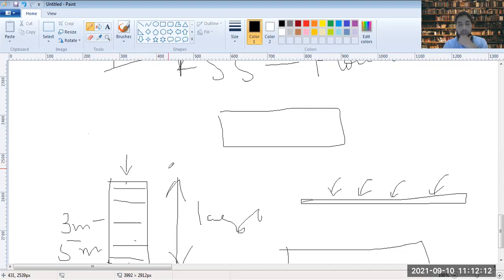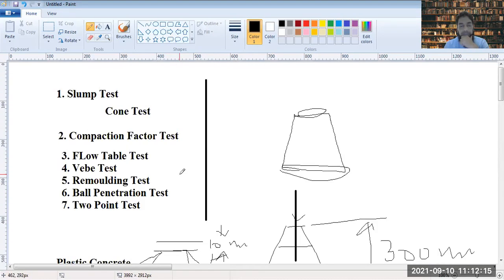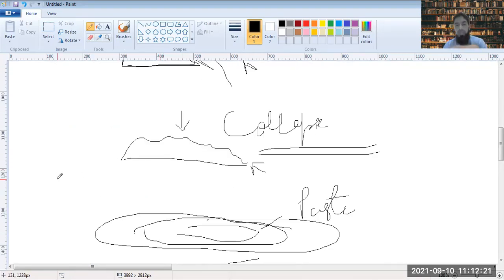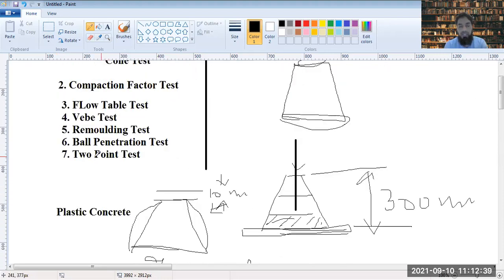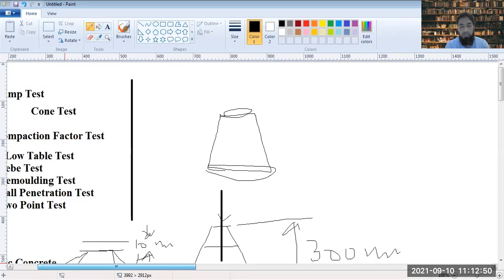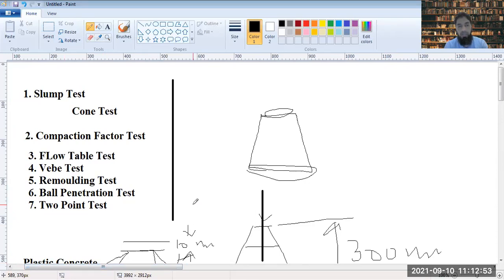Thereby, what is to be noted from this slump is that it gives you an idea of the workability, because workability itself is not quantitative, it's a qualitative property. It tells the quality of the concrete. But to put it in terms of quantitative behavior, so that we can measure it, we use this test. It's an indirect method to determine the workability. Otherwise, it's not giving us the workability, the ease with which we are working. It's giving us something else, which is known as the slump value.